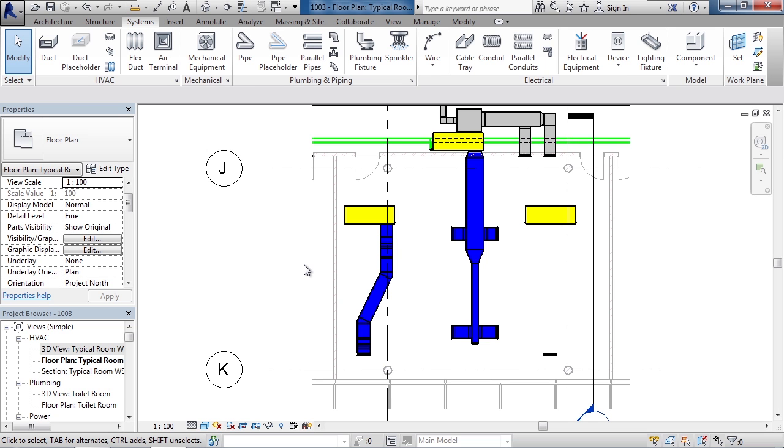Another thing is that placeholder ducts do not have values for things such as the justification for placement, insulation, or lining. Primarily, it doesn't have these things because a duct placeholder line is typically used just in the conceptual stage of laying out a project, basically where I just need a placeholder or a rough idea of where it's being placed. In comparison to the duct that's on the left, we're going to use the duct placeholder to do the same thing to the actual unit in yellow on the right and the diffuser air terminal on the right.